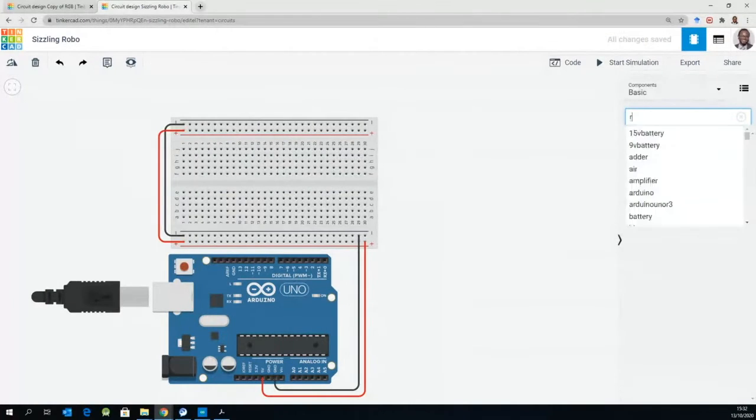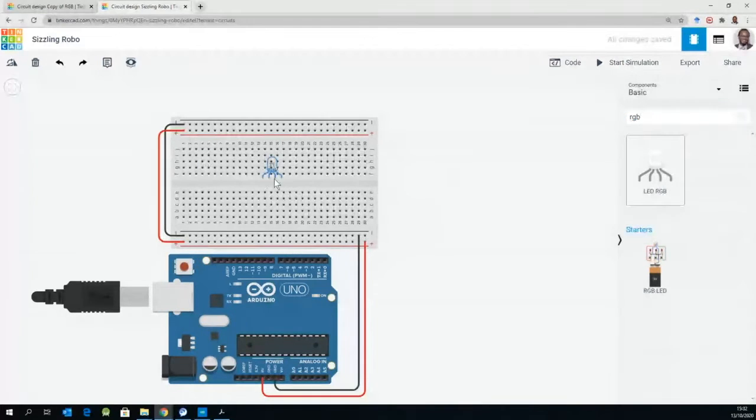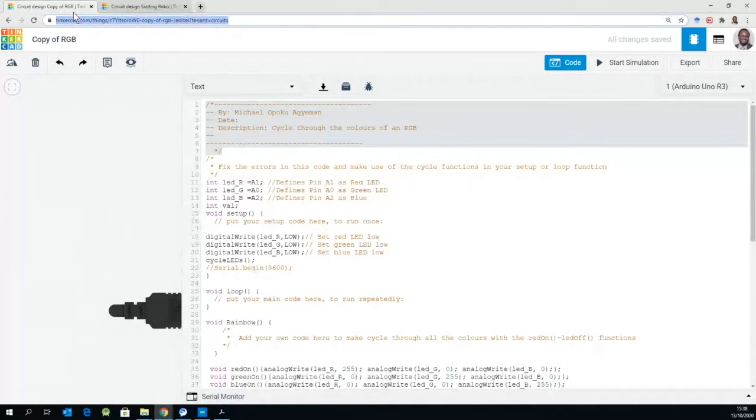Question, how do you know where to put your RGB? And the question is anywhere on the circuit as long as you are on the PCB or on the breadboard, as long as you don't short circuit it. So I just pick a random place on this column section. Note, you don't put it here because you create a short circuit. If you're unsure, just hover your cursor over it. You see the full connection. Doing the baby step or the step-by-step approach.